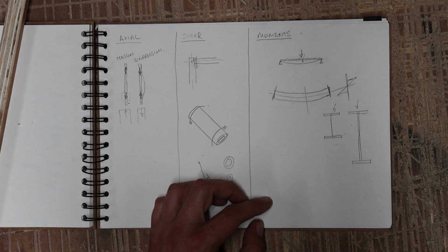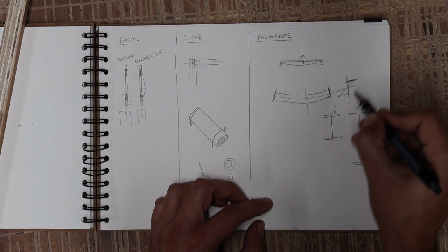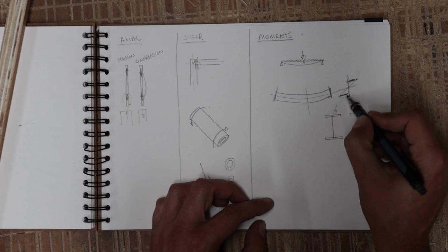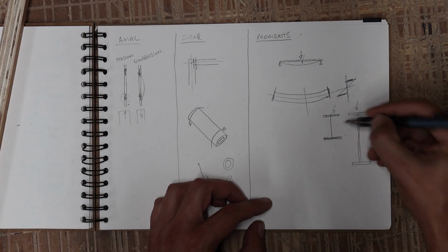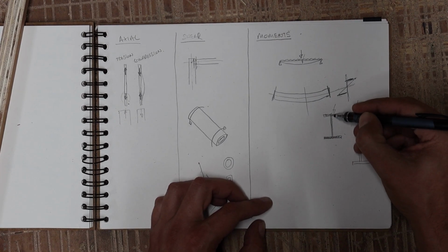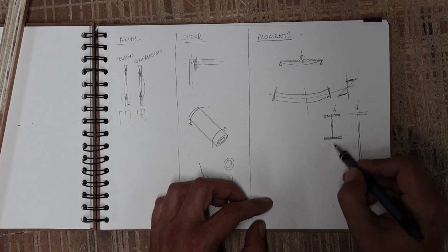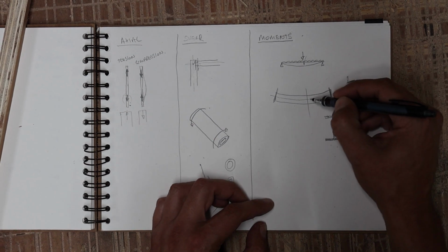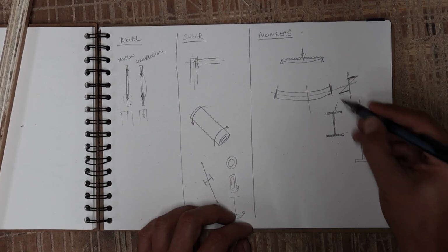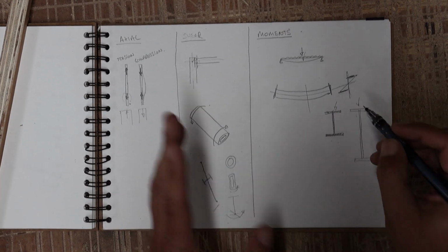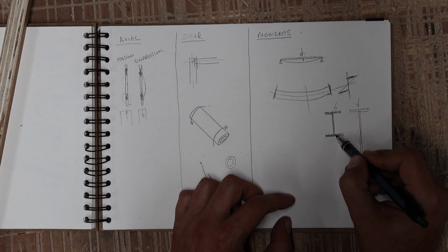But that's why we have these I-beams, because we have this peak force at the top and this peak force at the bottom, and we want some big chunky members to be able to take that force. This part in the middle is really just there to connect the two together. That's more or less what it's doing. I mean, it's doing a lot more. It's taking shear. I'm not going to get too specific, but the main thing that the structure of the beam itself is doing is taking that tension and that compression.